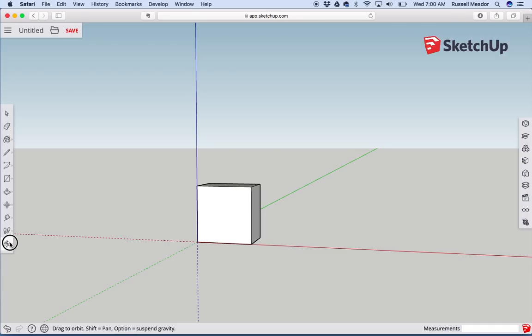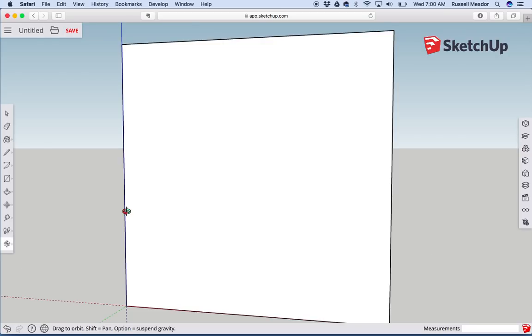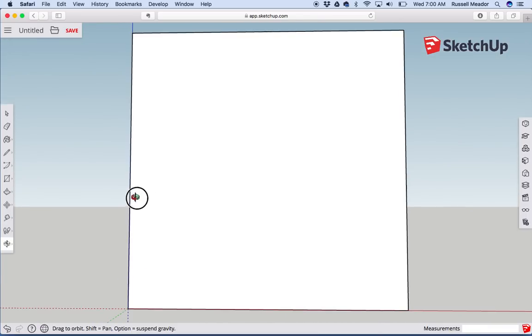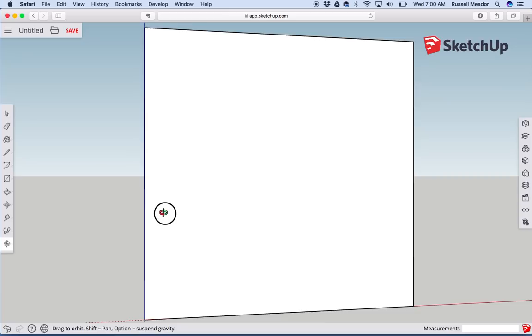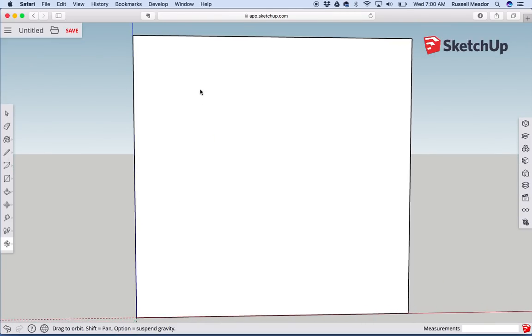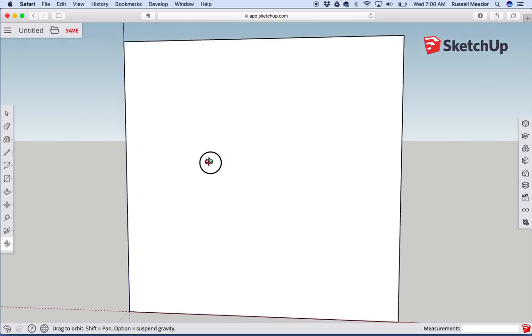So to zoom, I'm going to click the orbit menu down here at the bottom, the view menu, and I'm just going to go down to the bottom here, and you see where it says zoom extents. It's a magnifying glass with 3 arrows, and when I click zoom extents, it's going to fill my desktop with everything I've drawn. So when I click that, it's going to bring that in real tight to me, so I can scroll around and see that model. And when I get into really detailed work, when I want to add the rails and stiles to this base cabinet, when I add doors, it's going to let me work up really close.